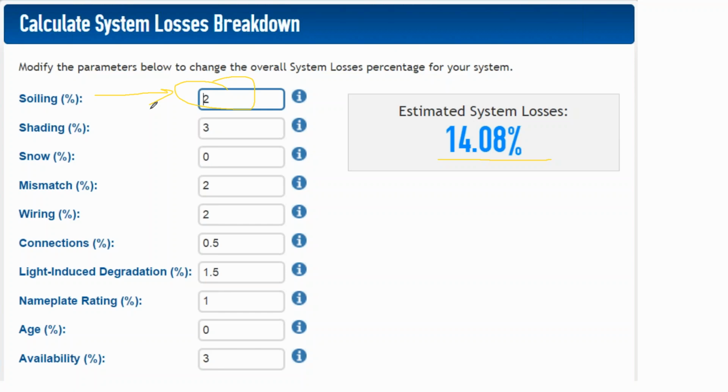In a heavily pollinated area, you can get pollen on your solar array. And the reason this isn't a huge industry problem is that solar panels can tolerate some dust and some pollen on their surface and still produce power. But you absolutely see an increase in power production of a few percentage points whenever you get up on the rooftop and scrub your panel with some water and a cloth. You don't really want to use anything harsher than that. You don't want to eat away at the water sealing of the panel, but we're talking about grime that can come off with some hot water, maybe a very mild amount of soap, not much.